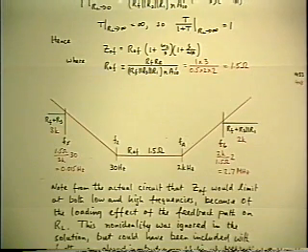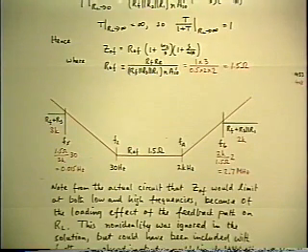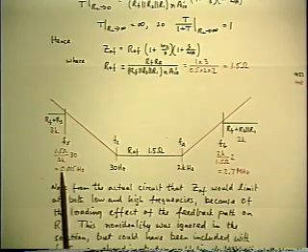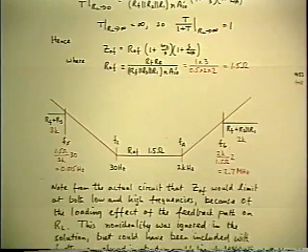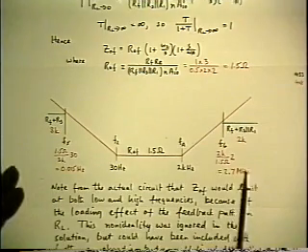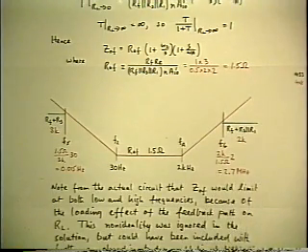Remember, we've included an output power transformer and modeled it with the turns ratio of n. And the transformer certainly is not going to have a conversion ratio of n at 15 millihertz or 2.7 megahertz. So besides the fact that we don't care what happens there, the model isn't right anyway.